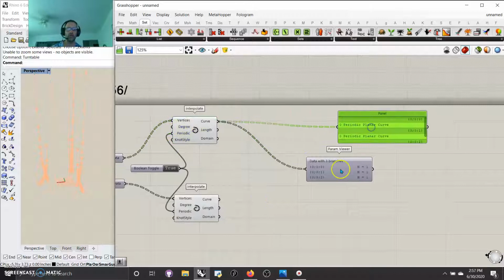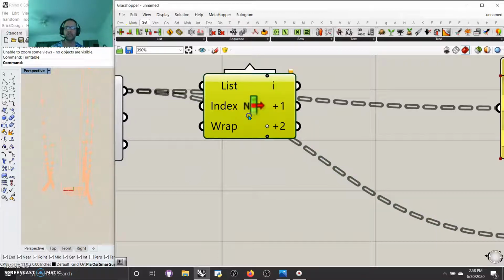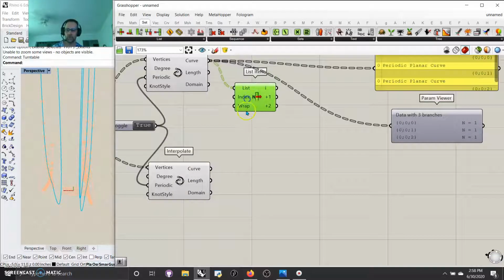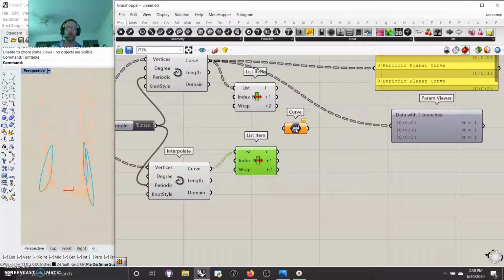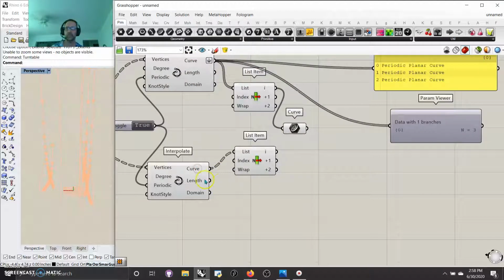They may not be in the correct order of what I want, and this is where I could get into a weave pattern, think logically what I want to do, but I'm a list item type person. So I will grab a list item and make 2 more items in that list, and I will grab those, and I will do that again to grab that item again here, and I will say I want to know what I'm grabbing as curves. This one. The one thing I have to do is, if you look at this, it's a list of lists. I just want a list. So I'm going to flatten that data and take that tree down a branch and put all the items into one kind of basket. Not flatten it completely, well, flatten it down to that.